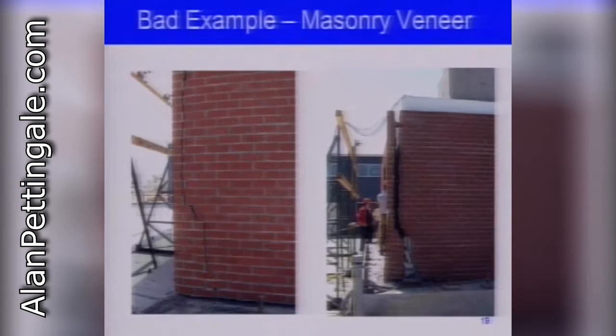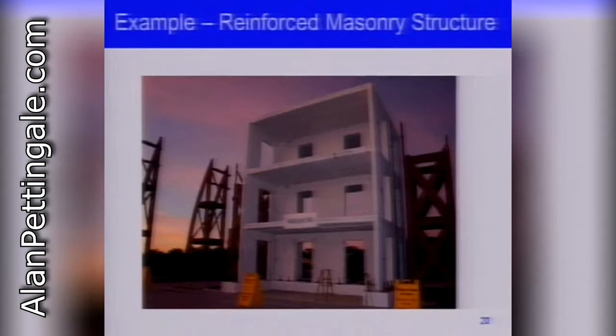You see that the initial crack grew larger and larger, and this was about to come out. So was that dangerous for the safety of the structure? The structure was okay, but if someone was to walk around it, there's a very good chance that this might fall, and that's a falling hazard. That's very, very dangerous. So that's a bad example. So we learned a lot from that test.